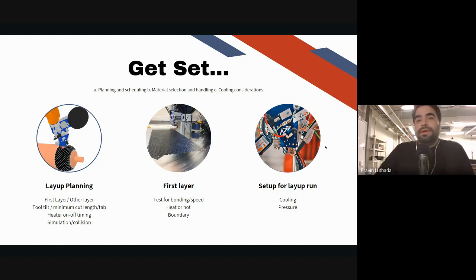Yeah, so I think we already talked about the first layer quite a lot, and definitely heat if possible, otherwise there is going to be some warping, and definitely put some tapes on the boundary. Yeah, I think now we are getting very close to running the layer. Now we come to the cooling and the pressure side.